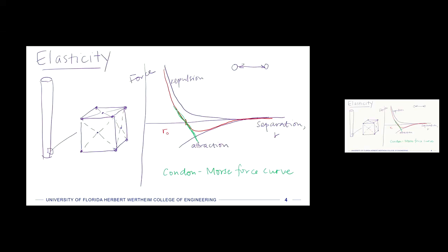So that's the theory. And we would say then, if at the atomic scale, I'm going to write an equation here. I'm going to say eta, which is that Greek n, is equal to whatever our separation is minus the equilibrium separation divided by the equilibrium separation, right? We were very familiar with these kinds of equations. We might say initially, oh, it's a percent error, right? Exactly. It is a percent error. It's also like the atomic engineering strain, right? Or it's called the fractional interatomic spacing.